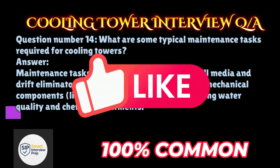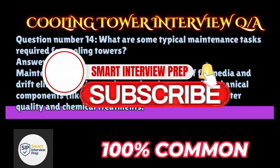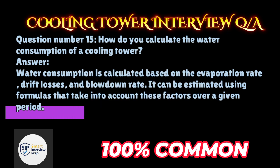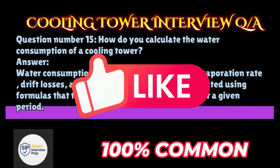Question number 14. What are some typical maintenance tasks required for cooling towers? Answer. Maintenance tasks include regular cleaning of fill media and drift eliminators, inspection and replacement of mechanical components like fans and pumps, and monitoring water quality and chemical treatments. Question number 15. How do you calculate the water consumption of a cooling tower? Answer. Water consumption is calculated based on the evaporation rate, drift losses, and blowdown rate. It can be estimated using formulas that take into account these factors over a given period.